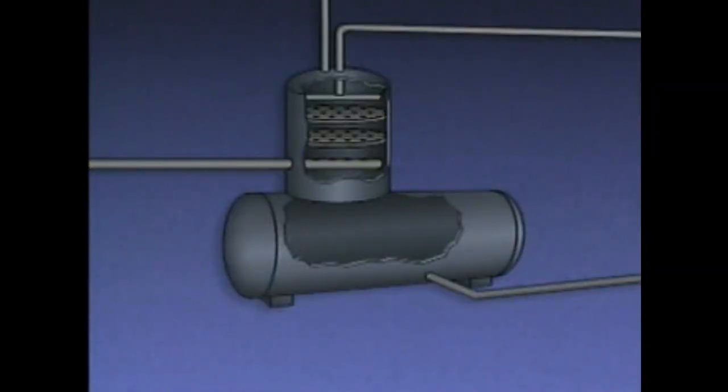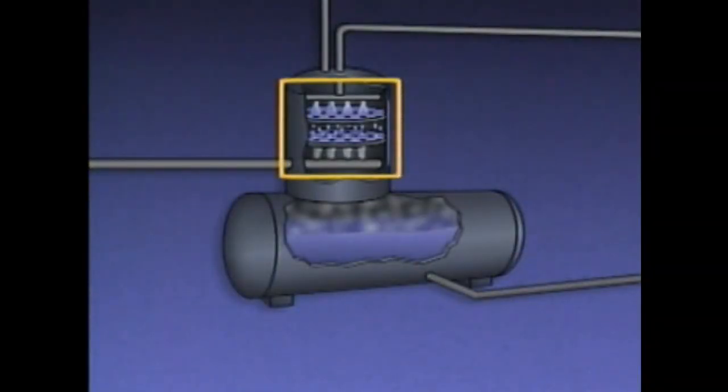During operation, water is sprayed onto trays in the deaerator that break the water up into small droplets. Steam is fed into the deaerator, and the water droplets are heated as they cascade down through the trays. The trays help lengthen the period of contact between the water droplets and the steam.